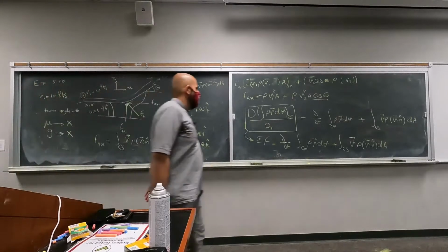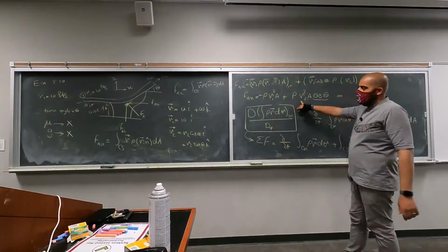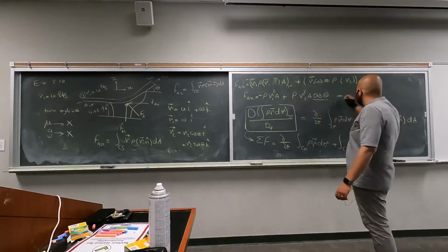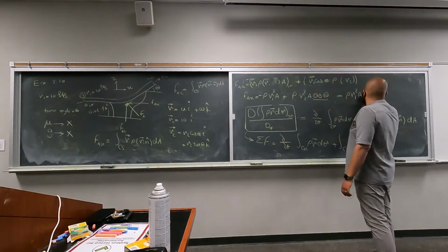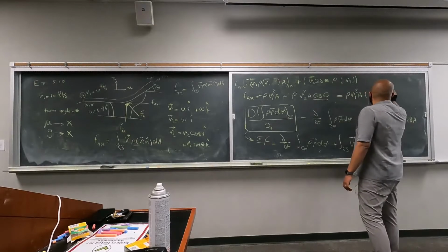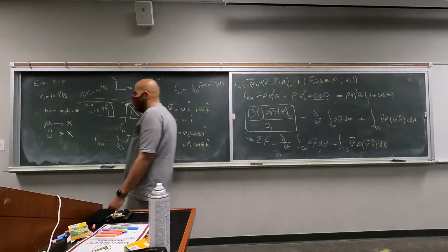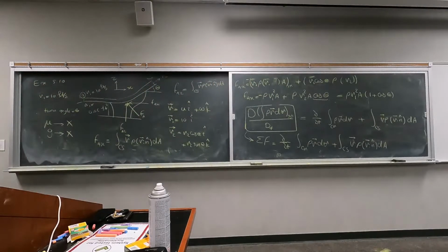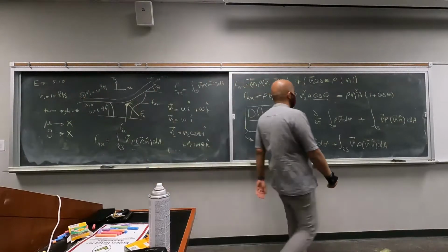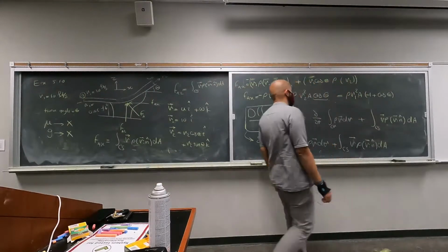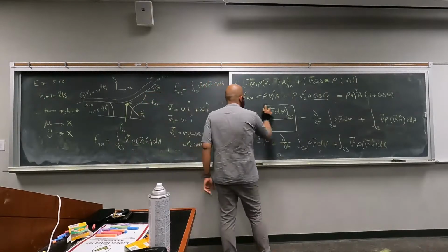Okay. So we can simplify this even further and replace V2 with V1. And I'm going to take V1 out. You get 1 plus cosine of theta. That's the anchoring force in the x direction. There's a negative sign. That's cosine of theta minus 1. Okay, let's do the z direction now.